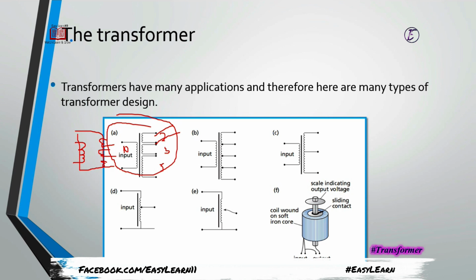And this is another way, where we are not using different windings but the same winding, with connections coming out from the winding that we can use. The same is the case: we can obtain different voltages depending upon our connection. If we take out the connection after just a very small number of turns, we get a small voltage here. It differs depending upon what we need.